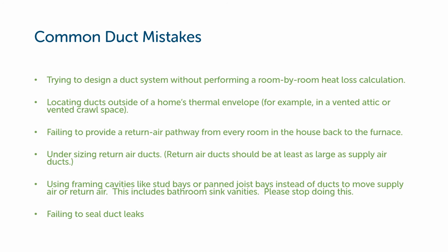And then they put a register in the toe kick of the bathroom vanity and they expect that little cabinet is going to act as a plenum. Doesn't work very well and it leads to a lot of duct leakage.